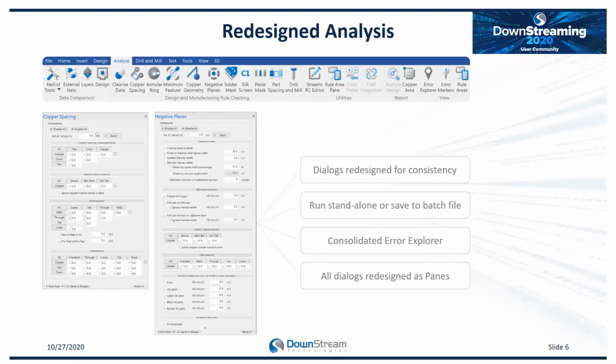Even though there is no thermal there, it will go ahead and run against different types of constructs here, pads, via pads, laser vias, and so forth, and report back if something like that occurs. So again, we can do these individually. If I just wanted to run that one check, which the user did, you could just come in here to do it, or make it part of my streams and run against every design.